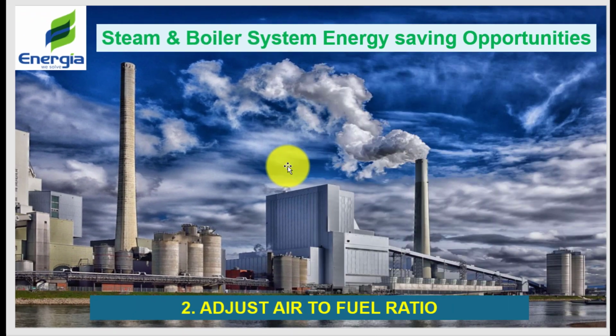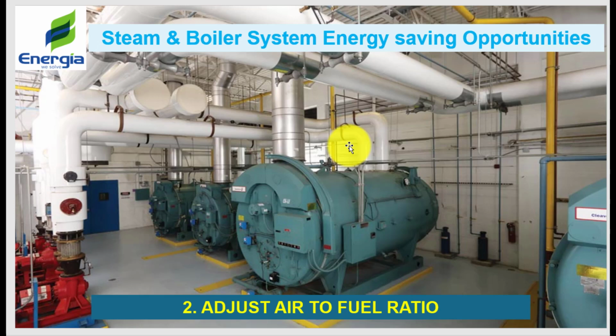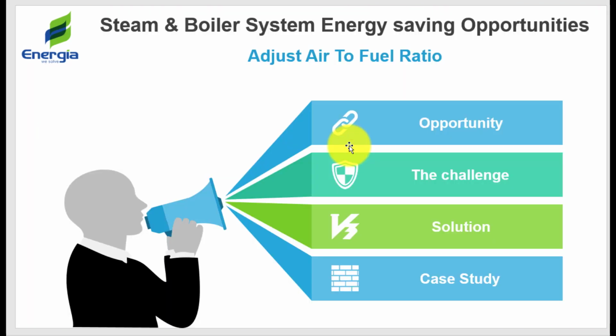Today we are continuing to explore other opportunities for steam and boiler systems related to energy saving, and this one is also a very frequent one. We can see it a lot in our cases in most of the industries, related to adjusting the air to fuel ratio. Actually, this is very important, and as I told you before, we usually take this through the same sequence